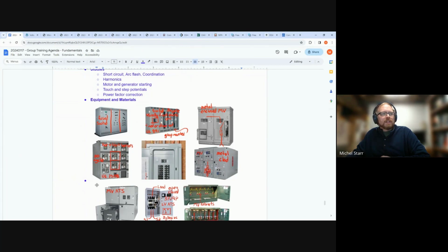So this is switchgear, UL, a different listing, UL 1558 versus 891. In this case, there are several compartments between every breaker. In this case, they don't, maybe just between some sections. So if you open this, all the cables would be near each other, and if there was a fault on one, it might impact the other. But of course, there's dollars that come with this. And then it seems to be deeper, so there are physical footprint situations for this.